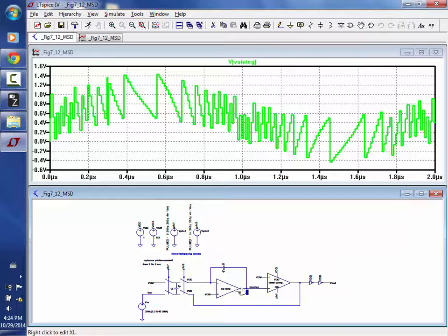You can see I'm using an ideal op-amp. It doesn't use a power supply. It's going beyond the rails of the integrator. Okay, so how do I make sure that when this is designed, it swings within the range? If you go work at a company where they design data converters and they use delta sigmas, they'll say, we only use SPICE for checking things like integrator output swing, like this node right here, because it's such a digital signal processing intensive thing. They do a lot of the design using MATLAB, because everything's basically like DSP, okay?